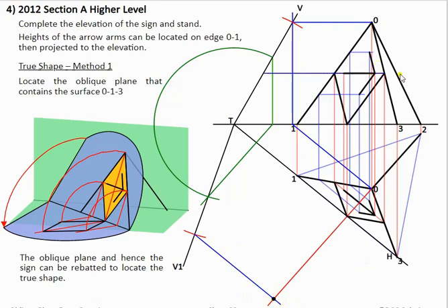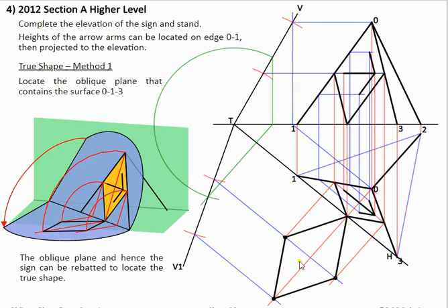Now we do the same for the center points. Bring them horizontally, rotate them around, then bring them back horizontally, and then bring out our 2 points. And then finally we have the base point already found, and that's our true shape of our parallelogram found on the ground. So this is the actual size it is in the question.